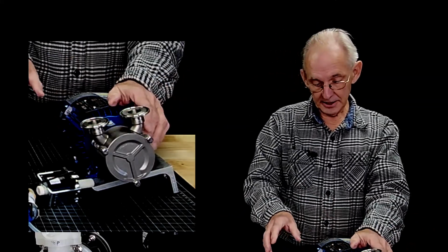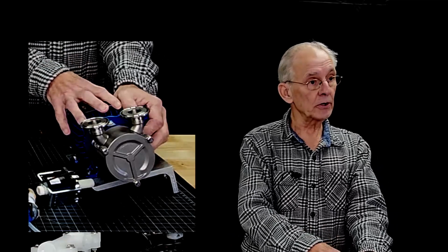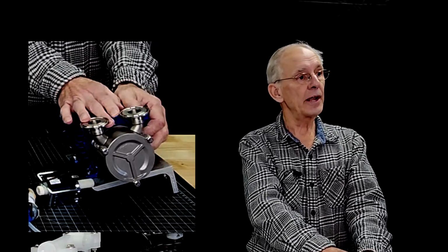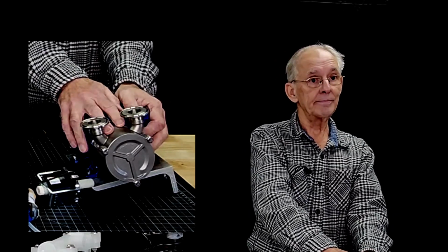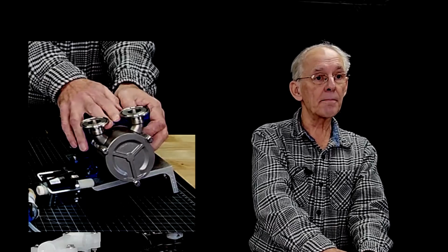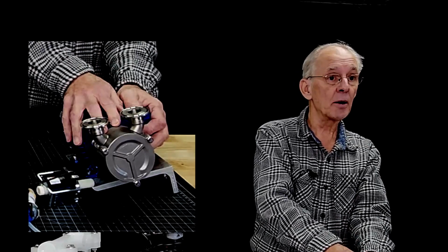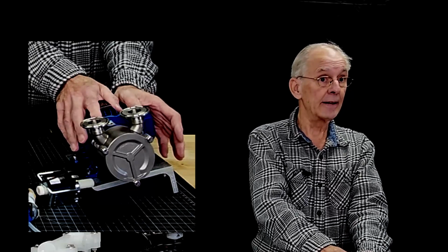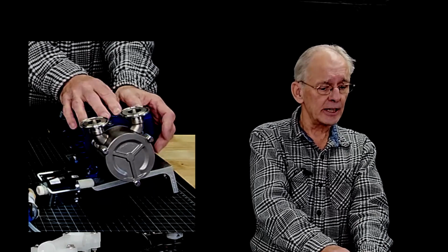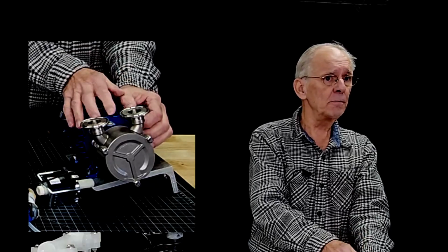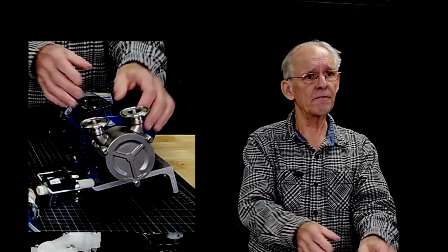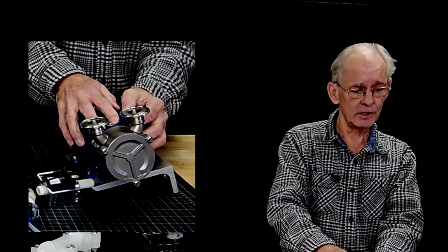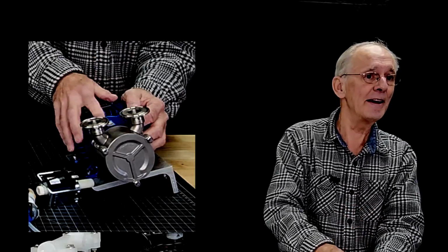Now, unlike the lobe pump that I showed you earlier, with this one there's no danger of blowing anything up because the pump is not positive displacement. It's limited in how much pressure it can generate. And the pressure it can generate is also a function of how fast you're running it. So that means that you've got lots of safety built in. You don't need relief valves and all these other complications. So it's a wonderful, wonderful pump for that application.